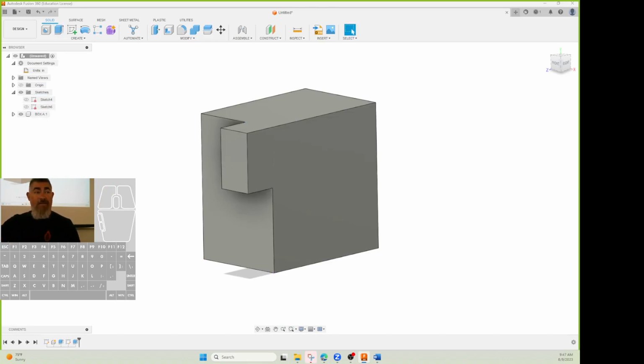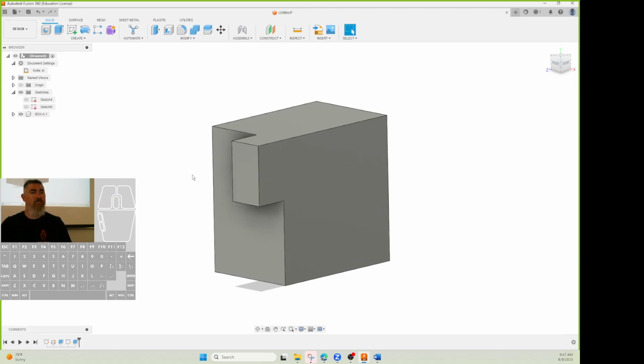That's because the intent is you use it, you leave it alone. So in most cases, use a sketch once, it turns off. If you need to do something else, just make a new sketch. Don't go back and do a bunch of stuff on that one sketch. There are times, there's always exceptions, right, when that sometimes is beneficial. We'll talk about that later, probably in CAD 20 next semester. Okay? So any questions on this?